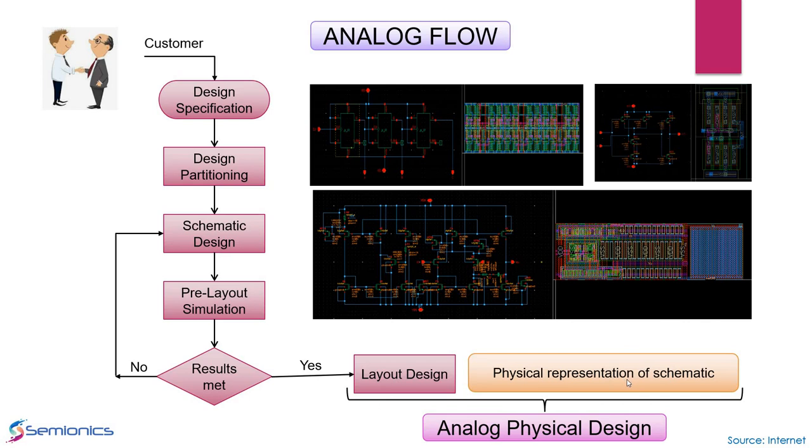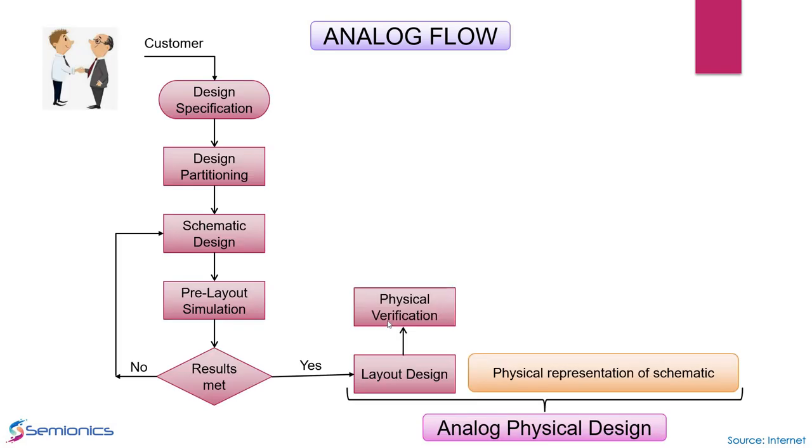Once this is done, the layout design is done. Obviously this has to be verified. It's not that you get a circuit, do a physical implementation, and it's done. It doesn't work like that. You have to physically verify it. So that is the next stage of our design flow. It's called physical verification.